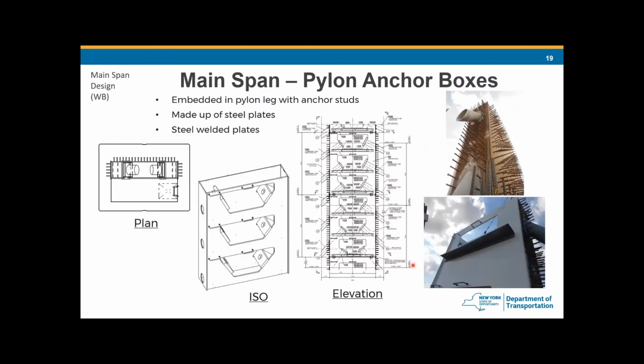And at the upper pylon, we have the steel anchor bars for the upper cable to anchor to the pylon. The steel anchor bars consist of 4 welded steel plates, and 3 sides of the welded steel plates are welded with shear studs, and these 3 sides of the plates are poured with the pylon concrete to make them composite with the pylon concrete. So the cable load will transfer to the steel anchor bars, then be distributed to the concrete.